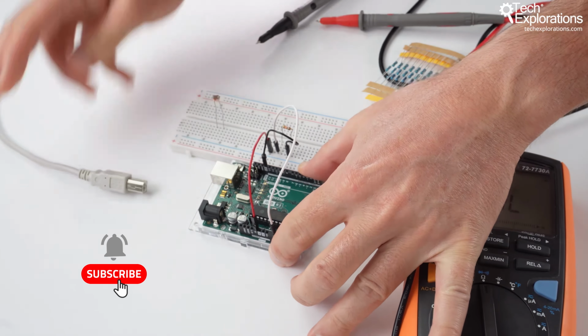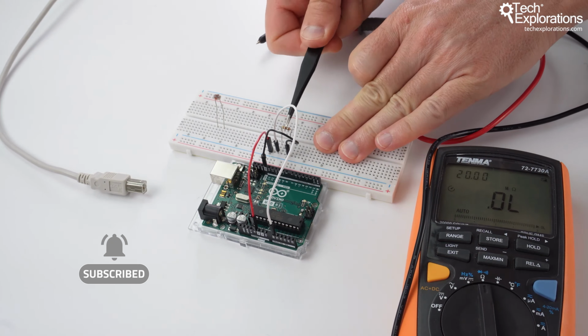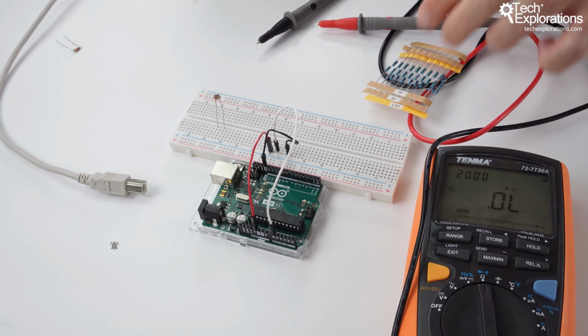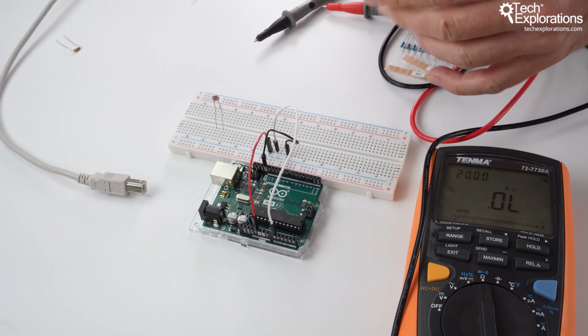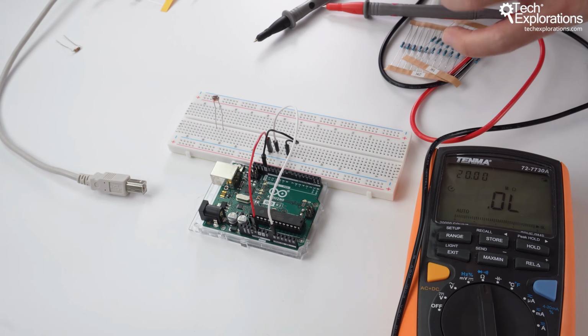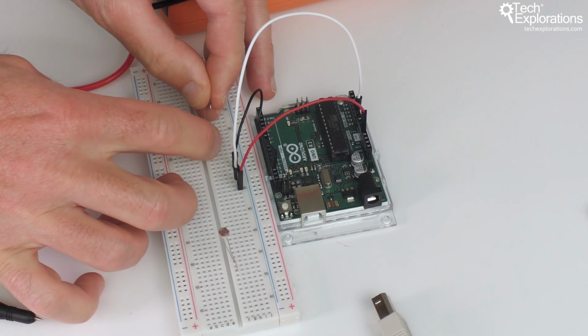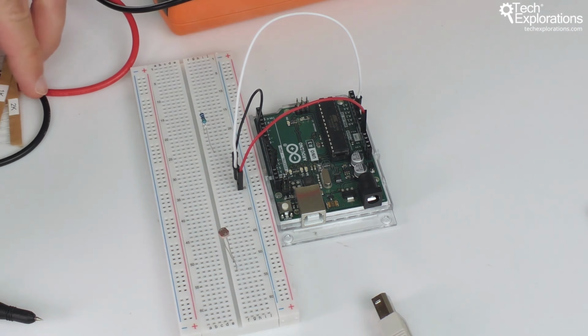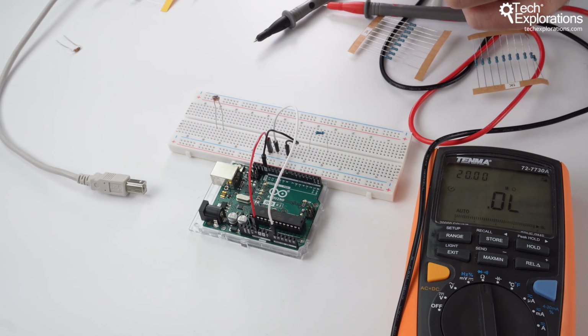So I'm going to unplug the power, remove the 10 kilo ohm fixed resistor, and then start assembling my new circuit. So let's go for the 5 kilo ohm resistor first. I'll go there. Then I'm going to go for another 2 kilo ohms.